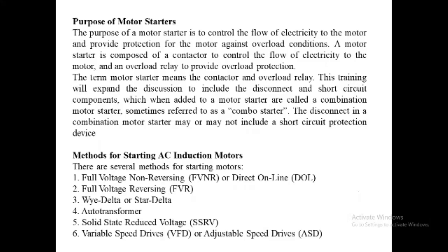This training will expand the discussion to include the disconnect and short circuit components, which when added to a motor starter are called a combination motor starter, sometimes referred to as a combo starter. The disconnect in the combination motor starter may or may not include a short circuit protection device.